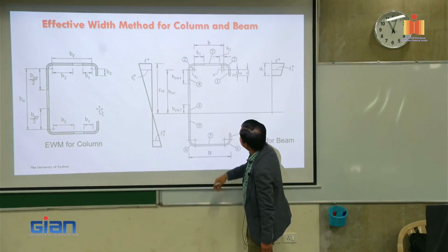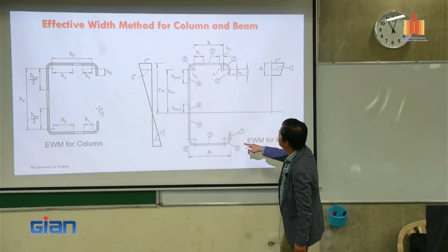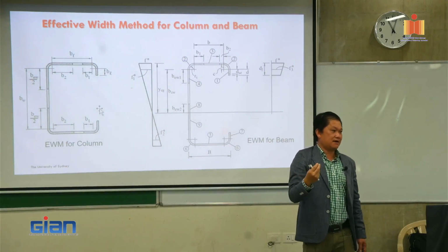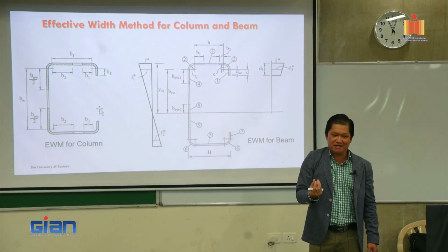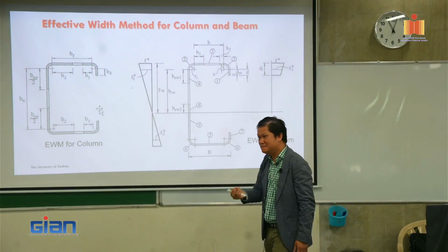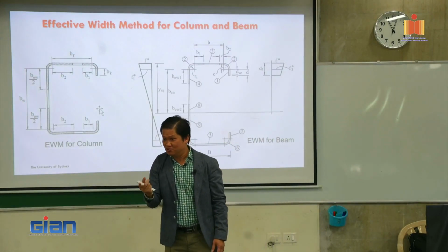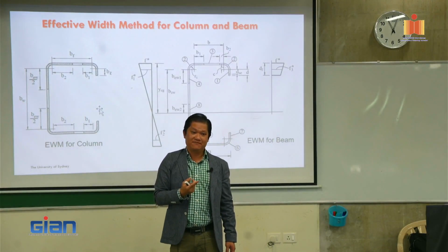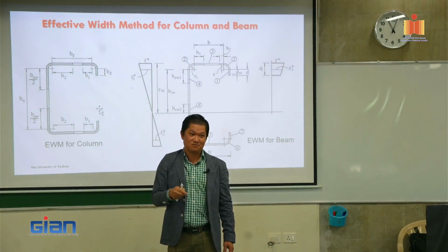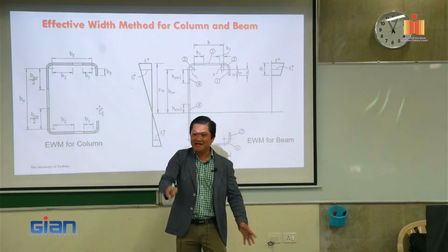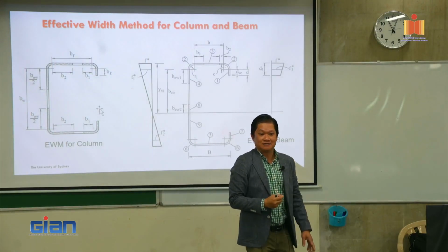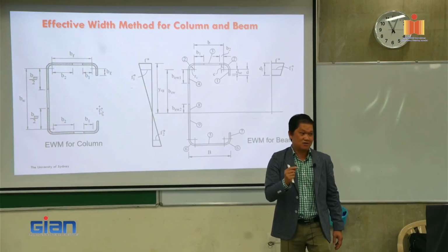Okay. So looking at this one, when you calculate the capacity of bending of the beam, what's important here is you have to calculate the section modulus, Ze, effective, right? So Z is section modulus. You need to calculate Ix first, that is the second moment of area. Then you back calculate Z, which is the section modulus.